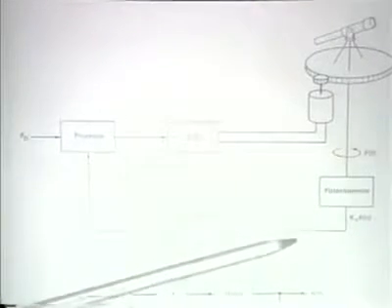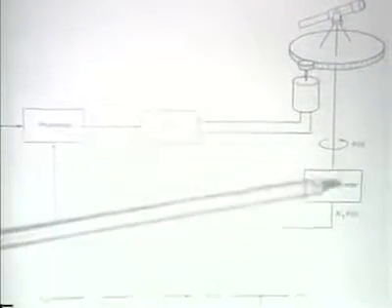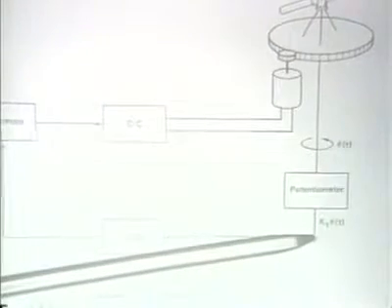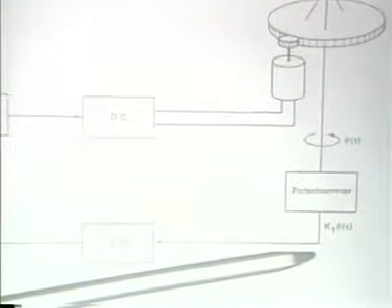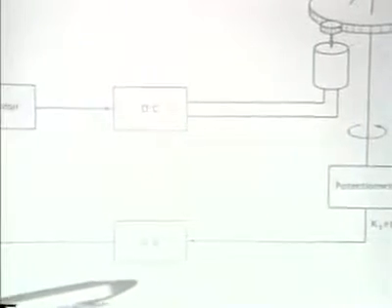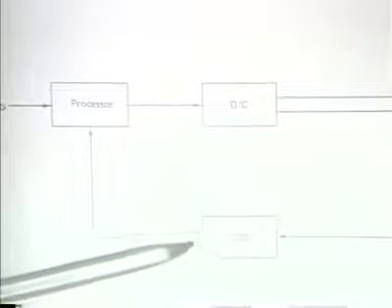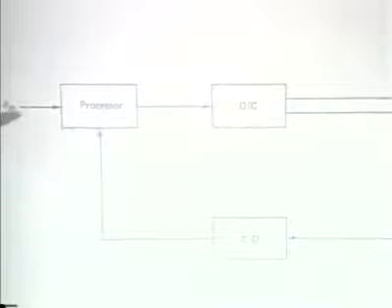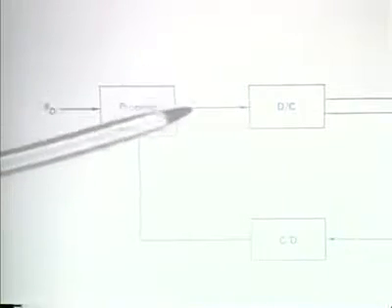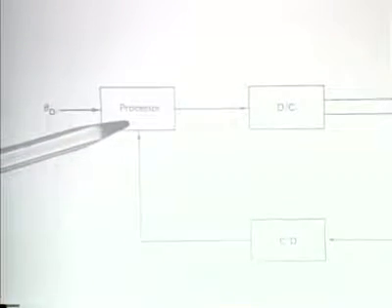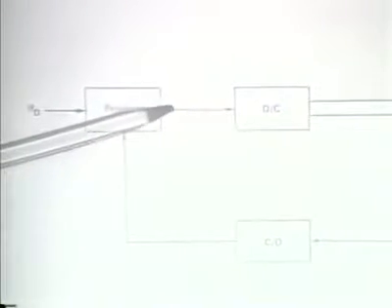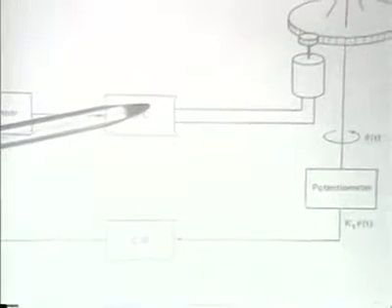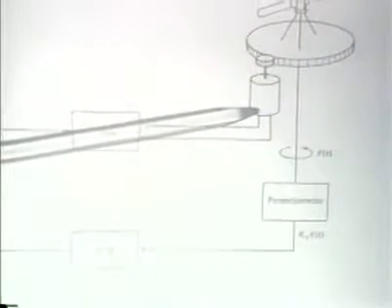And so in that case, we would basically take the position output as it's measured, sample it, essentially convert that to a digital discrete time signal, and then that is used in conjunction with the desired angle, which both form inputs to this processor, and the output of that is converted, let's say, back to an analog or continuous time voltage and used to drive the motor.